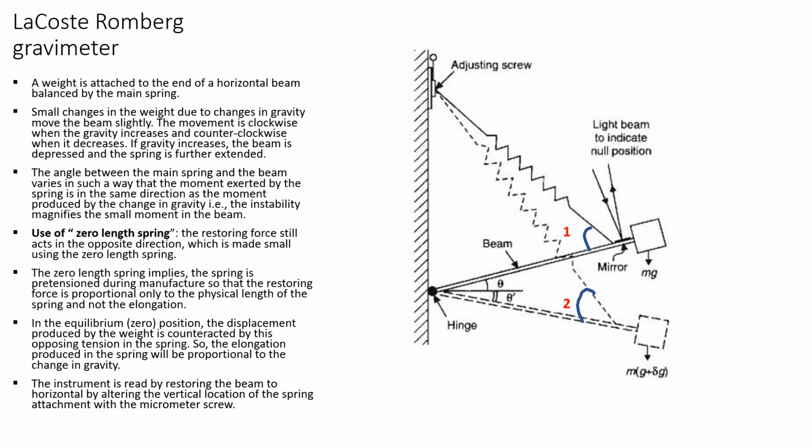It is this angle between the mainspring and the beam which determines the movement exerted by the spring, and the movement exerted by the spring is always in the same direction as the movement which is exerted by gravity. So if you look at the angle 2, in this case the movement, that is rotating torque or just torque or rotating force on the beam because of the inclined nature of the spring, is in the same direction as the change in the value of gravity, that is clockwise.